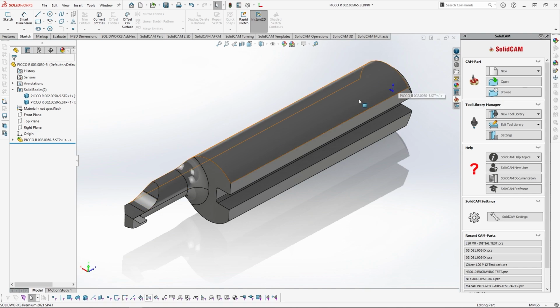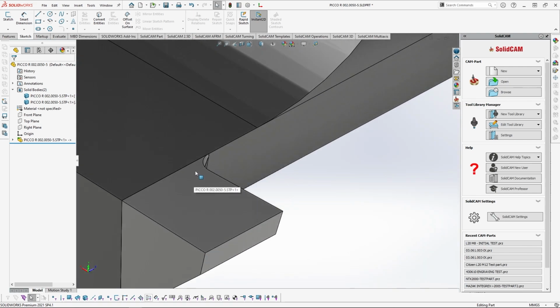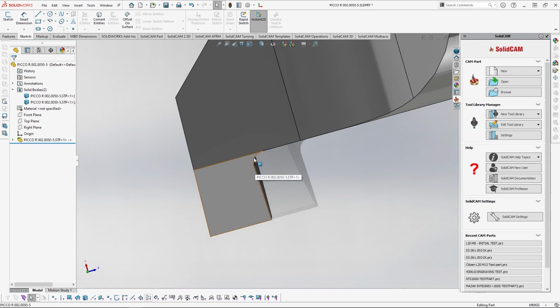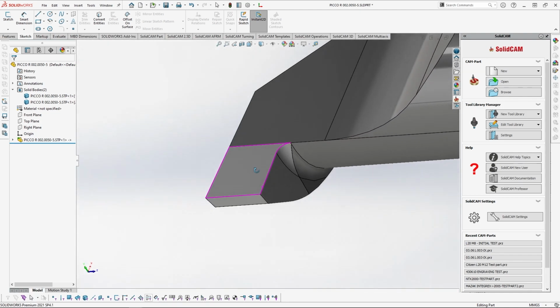Now, before creating these coordinate systems, I would like to take one note. This tip over here is a good shape, but it has this round feature that in some cases will not detect the correct tip, because it has the fillet here, and it might be that the center of this fillet will be detected instead. We want to avoid this situation, so that's what I'm going to do first.